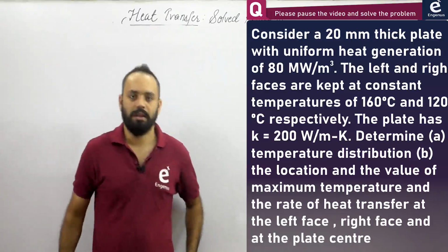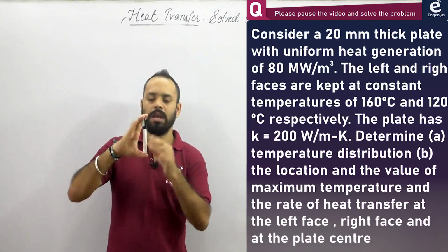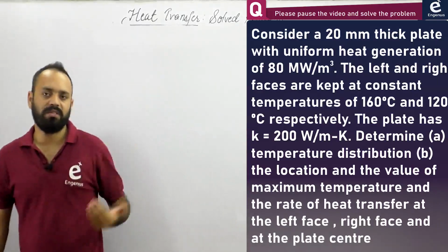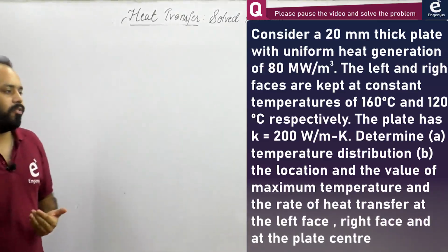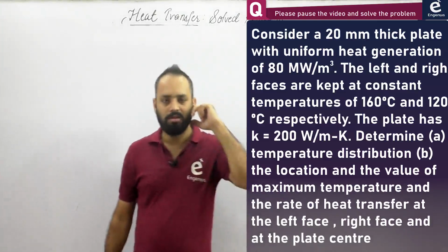were increasing linearly actually, right? Whose height was increasing linearly. It's like here the duct height was this and here the duct height was linearly increasing. So there also you can use the same concept, but please note that if the sides are increasing linearly, it's not necessary that area will also increase linearly.